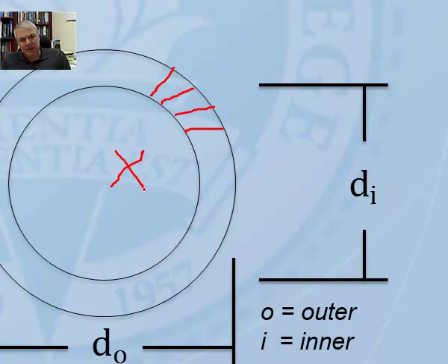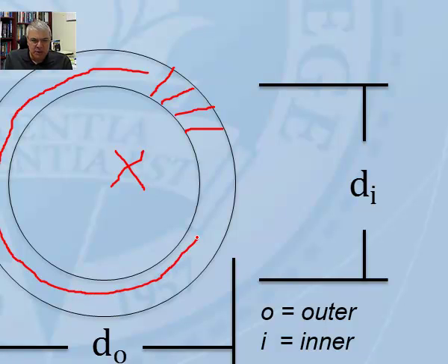At the center, the circle is empty, so we're dealing with the area near the perimeter of the cross section, and all these areas that I'm showing, I'm trying to draw the line inside the solid section of the bar here as shown. In that case, the moment of inertia would be pi divided by 64, d for the outer minus d sub I, so that's the part that's solid.